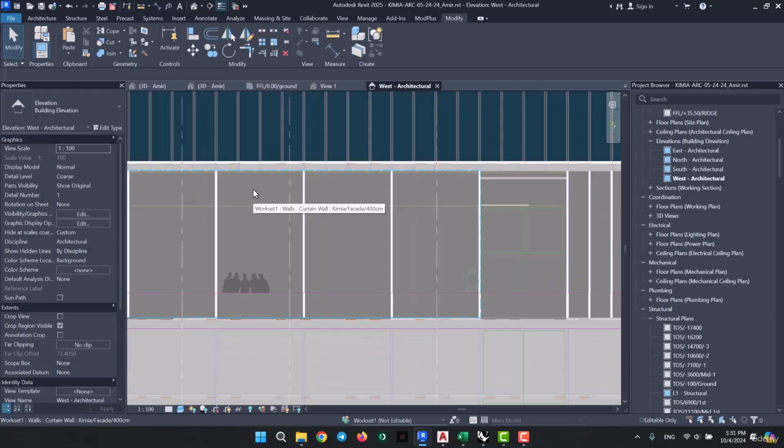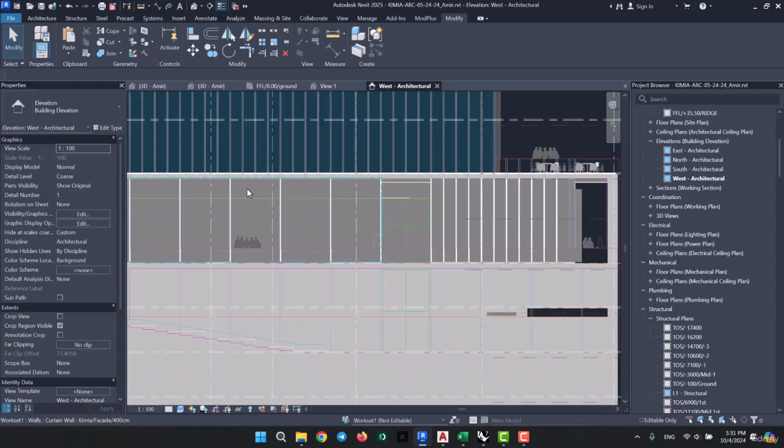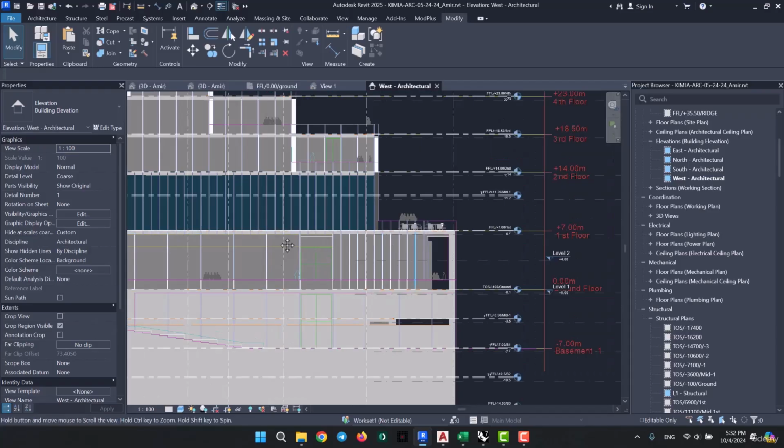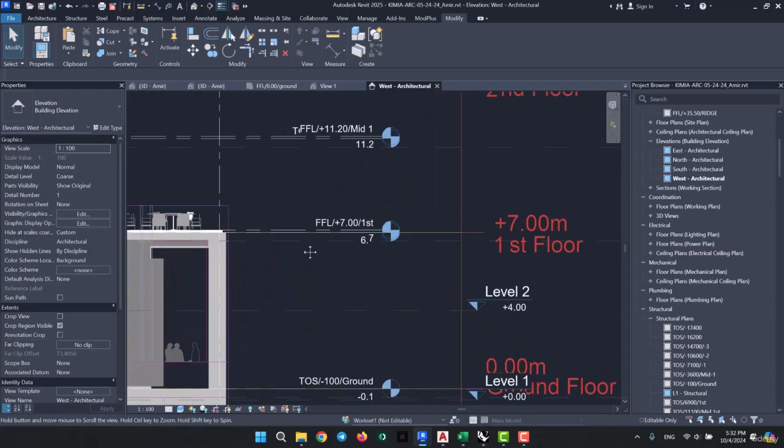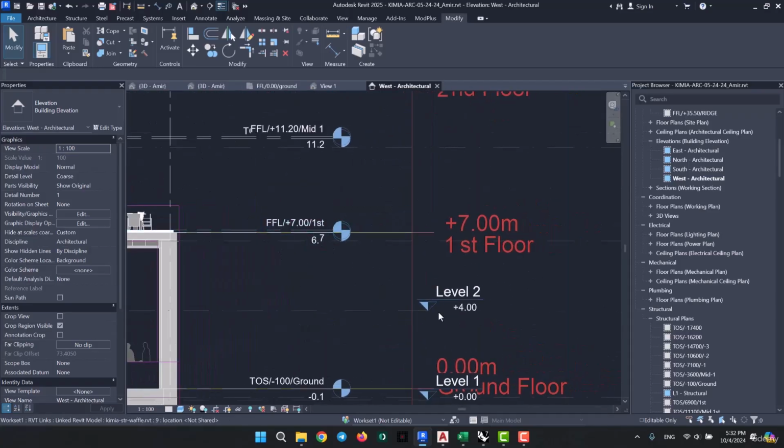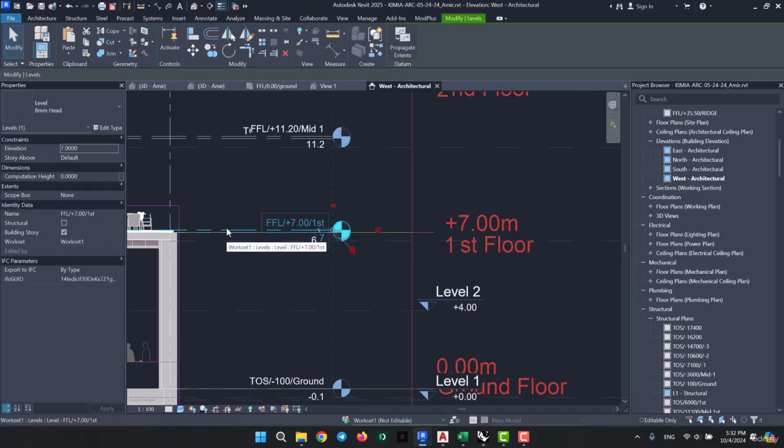This is where you'll have to go back to your plan and double check one more time, to see if you're the one who made the mistake, or if there's a problem with the plan. So the first thing I'll check is if I made the mistake. I'll start by taking a look at the levels I have available. The problem happens to lie here in the first step, which is that this yellow line over here belongs to the first floor in AutoCAD, whereas the first floor level lies right over here. So you can see that there's a difference between them, even though we did align the CAD plan with our drawing in Revit.